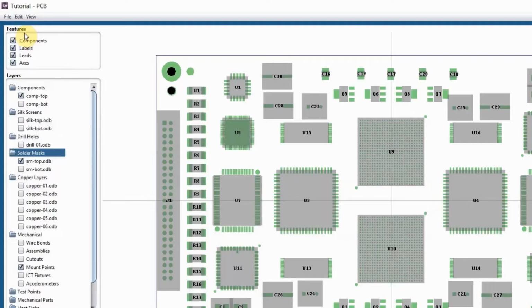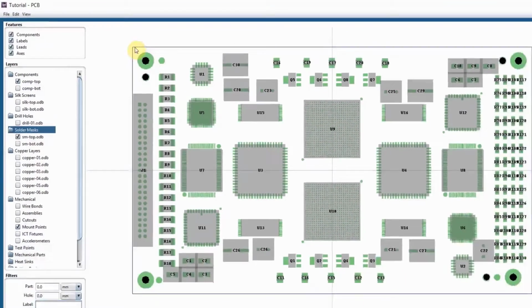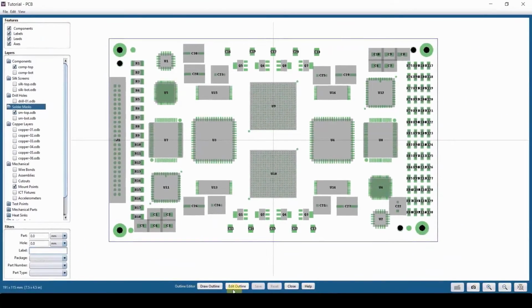Next down the menu is board outline. Usually this is a perfect 90 degree board here, but usually you have curves. When you have curves, you have a lot of nodes that you usually want to delete some of to clean it up. It makes your simulation calculations much faster and much easier. So you go to edit outline. You see I have one node here. If I create a few nodes here, I'm holding a shift key and click on one of these nodes and drag. It will give you a new node.